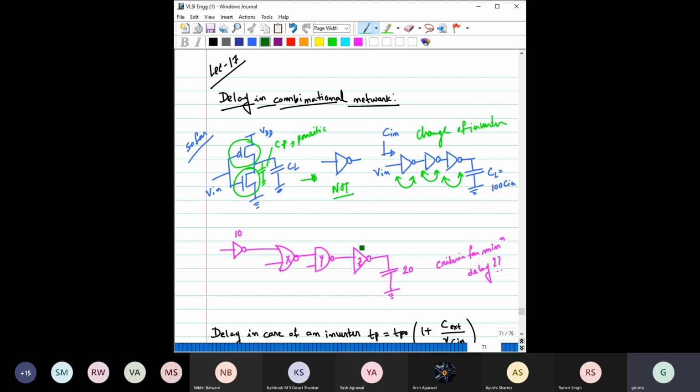Consider this circuit. There is only one path from this input to this output, and this is that path. Suppose this gate has size 10, meaning 10 units of capacitance, where the unit C is defined in terms of the smallest transistor dimension, for NMOS.